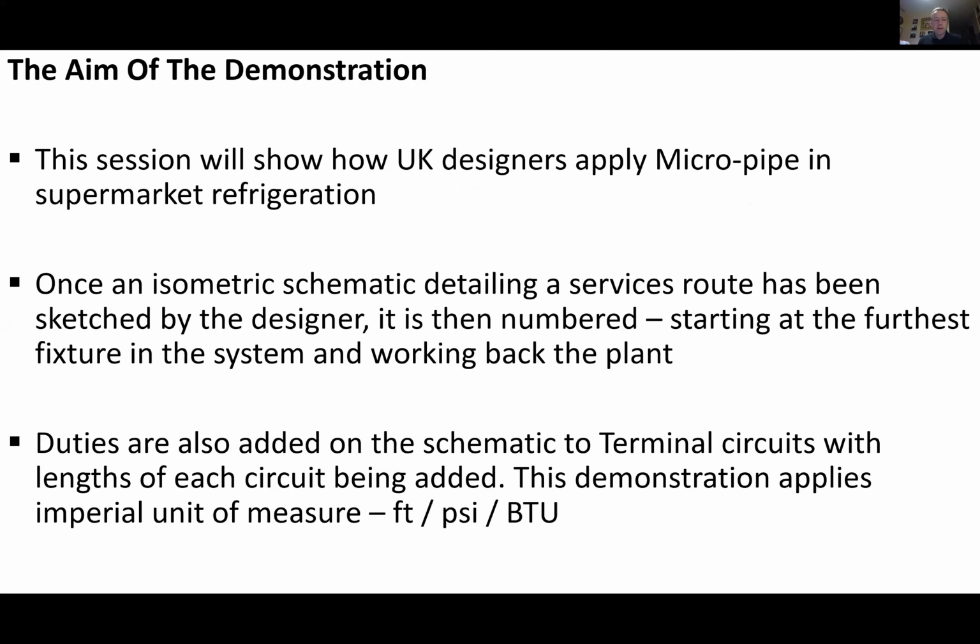In the UK, what we would look to do, a design engineer would typically sketch out an isometric schematic drawing detailing a service route by the designer. The design engineer will then number that schematic, starting from the fixture that's the furthest away in the system and then working back to the plant. Indeed, we'll see this presentation brings to life and helps articulate that specific bullet point. So duties are also added onto the schematic to terminal circuits, with lengths also being added.